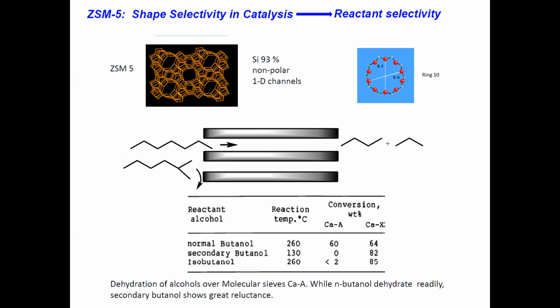So this is very, very important in the petroleum industry. Most of the plastic related things, at least the precursors for anything which is plastic or organic, the source is petroleum. And when you get petroleum, it has many, many things. It contains all kinds of hydrocarbons. So they have to be separated. So zeolites are widely used for separation. And this is the principle. The size selectivity is the principle.